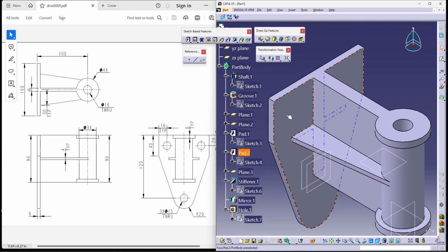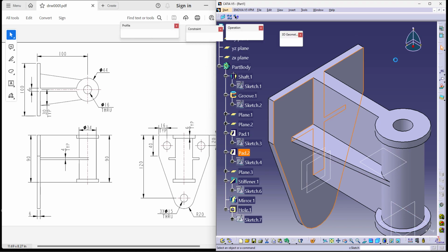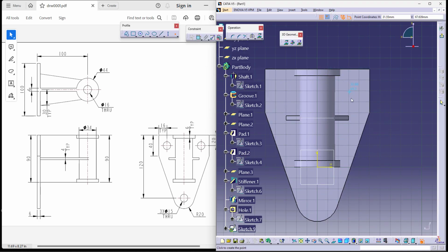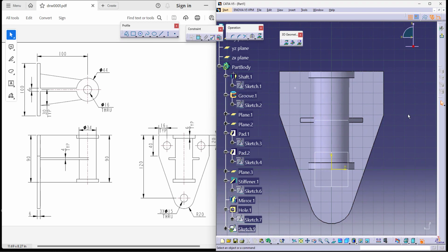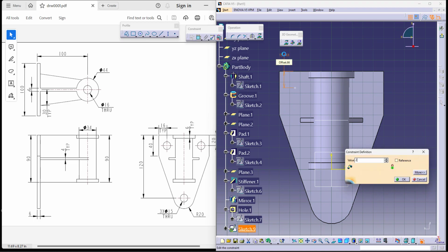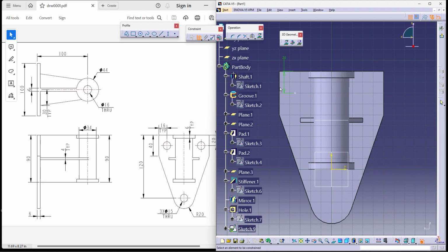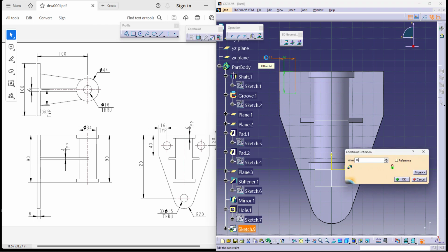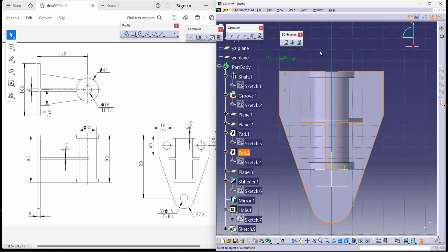Similarly, there are 3 over here. So I'd like to make a sketch so I can use a user pattern instead of doing it multiple number of times. So this is the first point which I'd like to keep and dimension it. This is supposed to be at 20 and supposed to be at 16 from this edge. And then I can mirror the same thing onto the opposite side. And then take another point which is exactly located concentric with this. So let's maintain concentricity with this arc and then say exit.